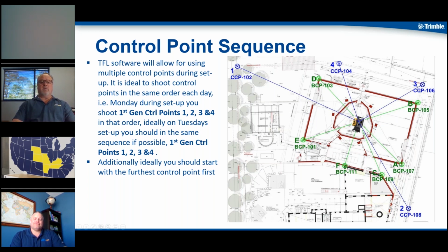All right. We're using corners of buildings on this one, and you can see that A, B, D, and E are the corners of the new addition. For C and F, we are using control points that we would use on an existing building. We would probably switch out of Prism mode and have stickers on the corners of those buildings and just shoot them in laser mode. Or you could create some offsets and create control points there.